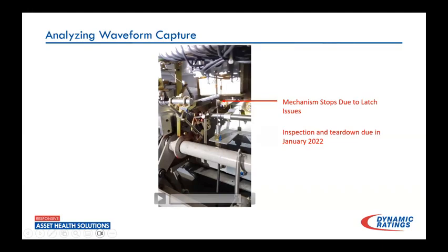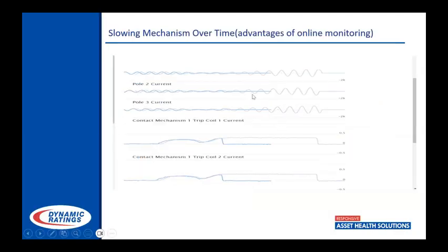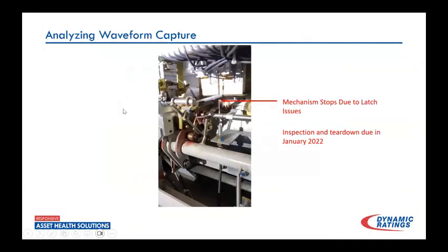So we can see this latch took a long time coming off, and we see it actually came to a stop right about here, which had, like I said, let this main cam initiate slightly at the beginning, but not enough to get clear. So we've got contacts that are sitting there, and if we go back, we can actually see through here, we have a lot of arc time going on in this breaker. So again, just a way of looking at the graphs and the captures of all the different currents and diagnosing the type of problem that we're seeing.